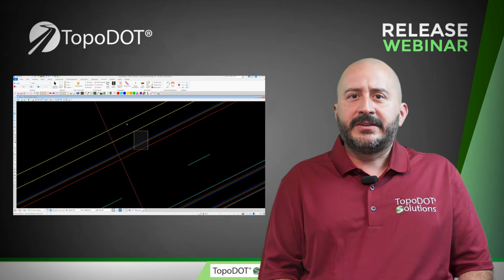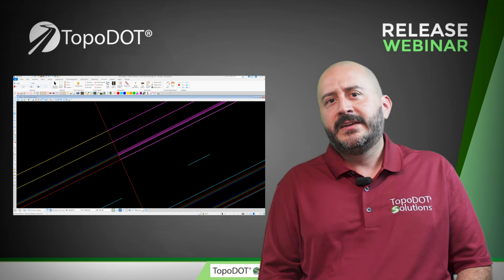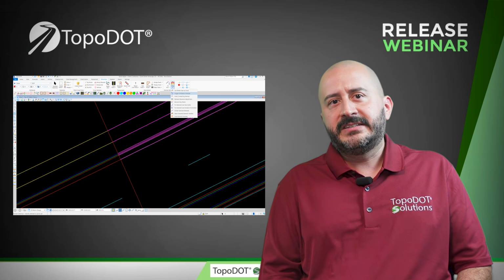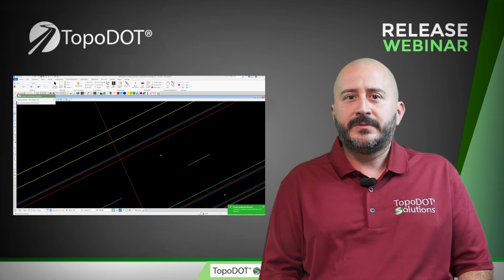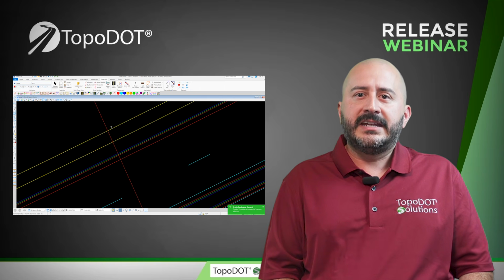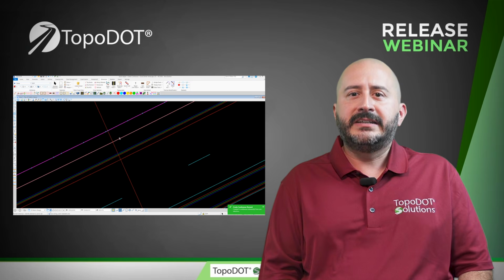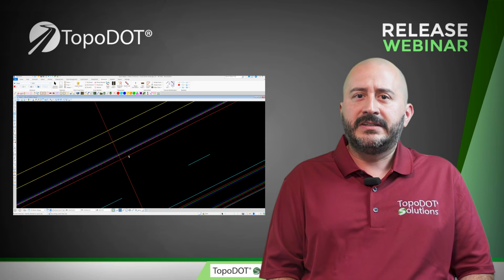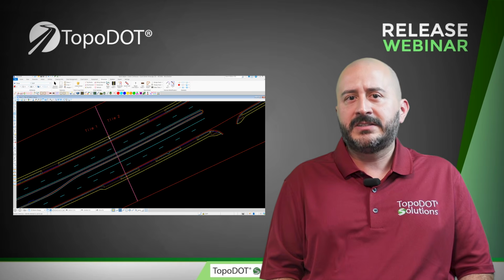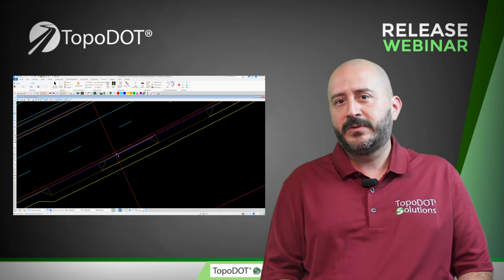Finally, let's talk about the Create Continuous Element tool. This is another modernization of an existing favorite, but we've packed it with new quality of life features to speed up your deliverables. For instance, you can now click anywhere on an element and the tool will automatically connect and merge in both directions. If you have a larger area to process, you can now execute multiple connections in batch simply by pre-selecting those elements before running the tool.